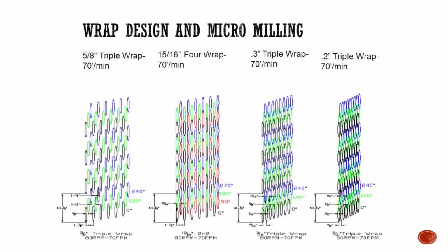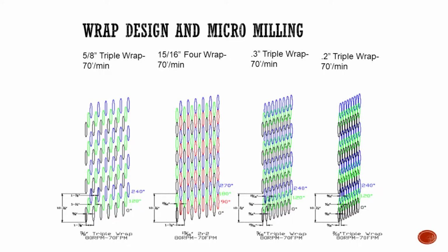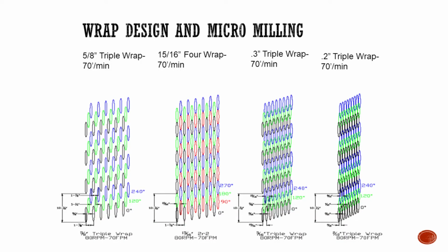And then you see here the wrap design with the forward cutting speed the same, but the variations of the different wrap designs. The 2 on the left side would be your standard drums, something like an all-purpose drum, being able to mill 6, 7, 8 inches, no problem, 10, 12 inches even. The 2 on the right would be your fine milling drum and your micro mill drum. Those are the ones where the spacing is much tighter, but you would want to keep those for specialty jobs where the benefit of having that super smooth pattern would outweigh the cost of running it.